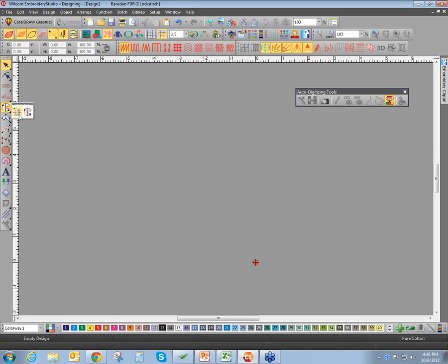Wilcom brought a tool to the market some years back now. I really love this tool. This is Fusion Fill. Fusion Fill is the marriage of those two tools in one, if you will. So I can literally plot my points. Then I'll do curvature points, right-click, left-click for straight. And I can input a hole. So maybe I'm doing kind of a weird funky D here. That's my entry point, my exit point.